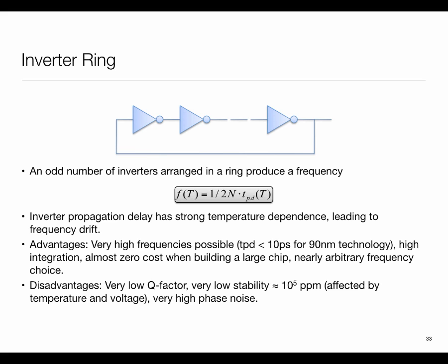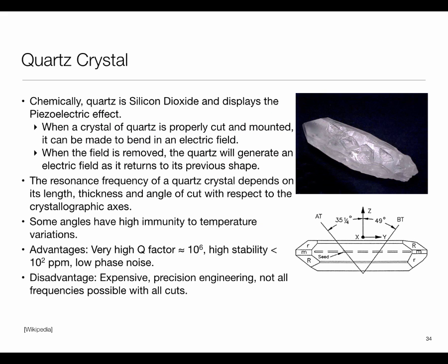And maybe the stability could then be achieved by disciplining this clock. That is, you can have a processor running this clock, but separately you can run some sort of a protocol, maybe NTP or something, which frequently synchronizes from something outside, and thereby this clock keeps correcting for the drift.